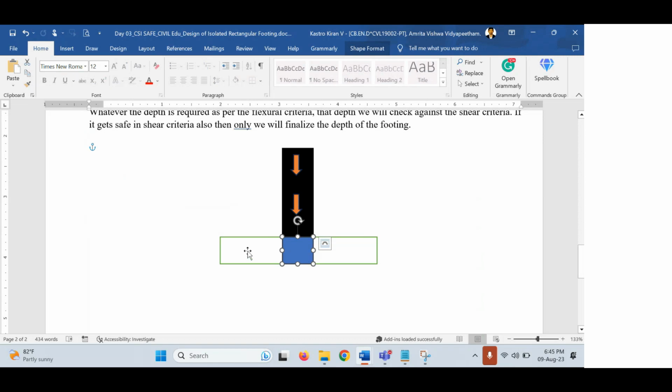The right side and the left side of the foundation slab will not experience that much load. They'll also experience it, but not as much as the stiff area. So that's why when you are designing the foundations, it is important to consider the stiff area. Now here you may have a question. Why will the loads not be here? Loads will be there, but what type of loads? The soil pressure will be there. You're going to cover this entire area with soil, right? You're going to pour the soil here. So the cantilever portions will experience the soil pressure that is coming from the top.